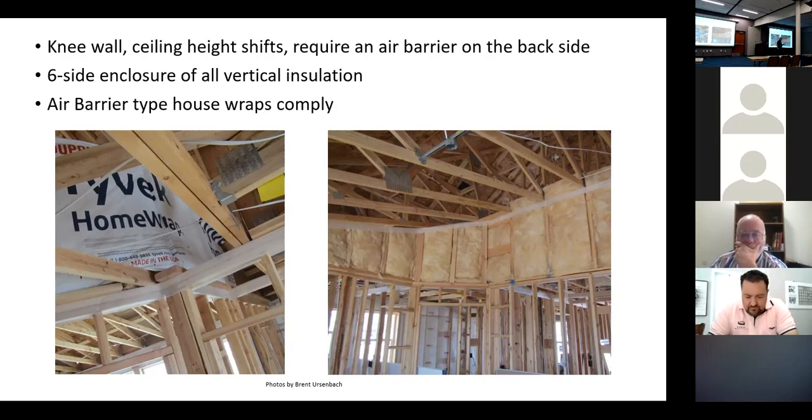Very common, you build a roof. If it's in Summit County or Wasatch County, the Park City area, what does everybody want to do? They want big high ceilings, right? So it's 11 7/8 or bigger TJIs, glulam beams, blow it full of insulation. Both the IRC and the IBC have requirements in there for unventilated spaces, and it changes for the climate zones. In the IRC, I think it's 808.6, but I can't remember for sure.